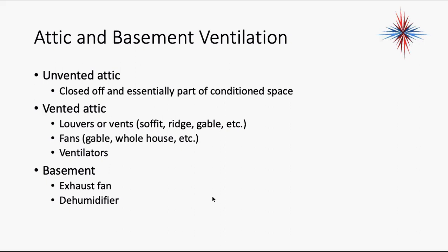Vented attics use louvers or vents: soffit, ridge, gable. There's a long list. They use attic fans. They use ventilators. In my attic here, I have gable vents, I have soffit vents, and I also have a solar-driven attic vent that sits on the roof that pulls air out on the hotter days.